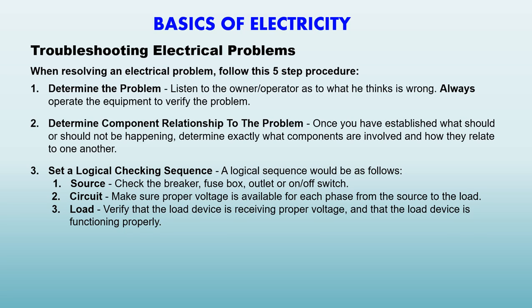Check the source. Check the breaker, the fuse box, outlet, or the on and off switch. Do you have power to your device? Check the circuit. Make sure proper voltage is available for each phase from the source to the load. Last, check the load. Verify that the load device is receiving proper voltage and that the load device is functioning properly.